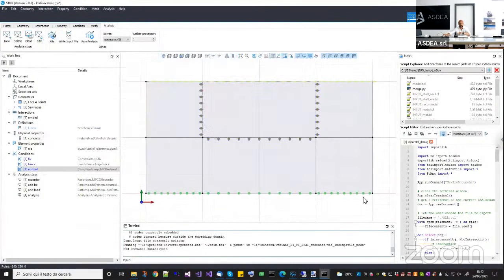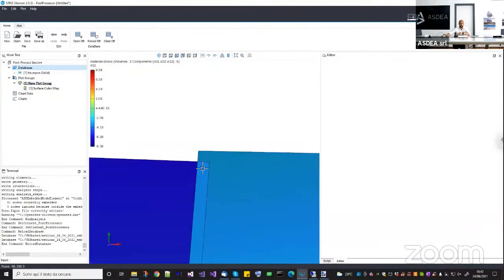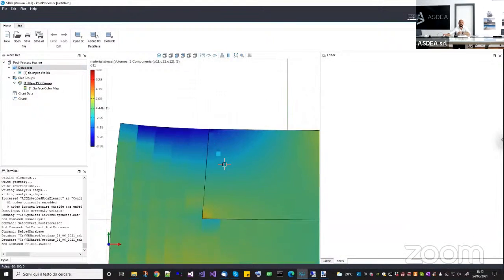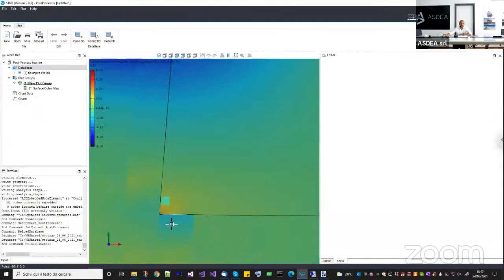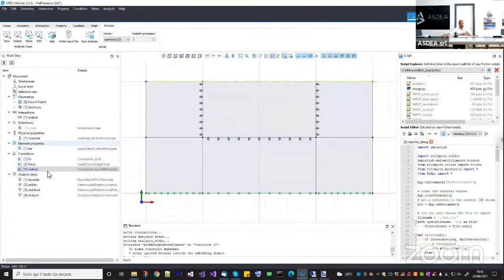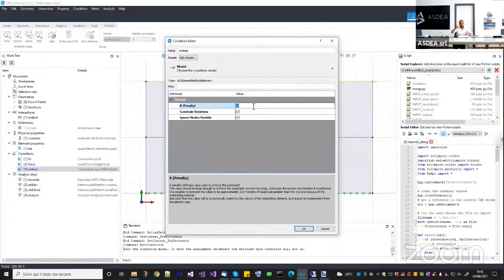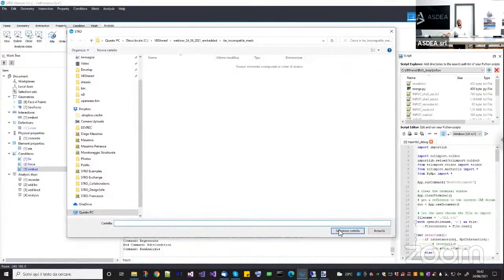Now it is 3 orders of magnitude less. You can see an increasing interpenetration and so on. And of course, then you will start having local stresses that are not realistic, okay? So the rule is it should be at least equal to the Young modulus, but I typically use the Young modulus with 3 or 4 orders of magnitude more. So I put the Young modulus here, which is 30,000, E3, okay? So I multiply it by 1,000, and this is a pretty reasonable number.